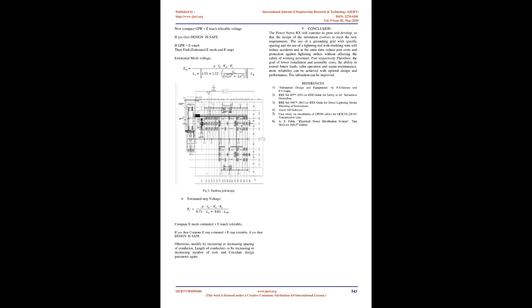Grid resistance. Typically, the site engineer specifies a grid resistance. Earth resistance should be as low as possible and should not exceed the following limits: power stations 0.5, EHT substations 1.0, 66/11 kV stations 2.0.